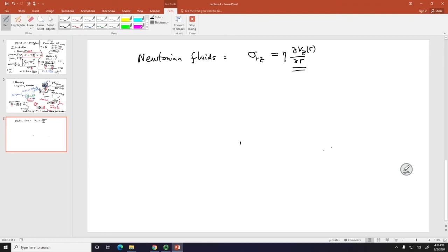When we talk about capillary rheometry, we typically do not discuss the fact that this die is of a finite length. It's not infinite. Only in the limit that we ignore what's happening at the end and at the entry can I say your velocity is only a function of r. In that case, a total derivative is good enough. We don't need a partial derivative.